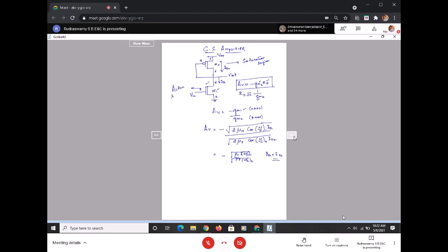Make sure M2, the PMOS acting as a load, operates in the saturation region. We should provide all these necessary conditions, and the NMOS has to be in the active region in order for amplification.